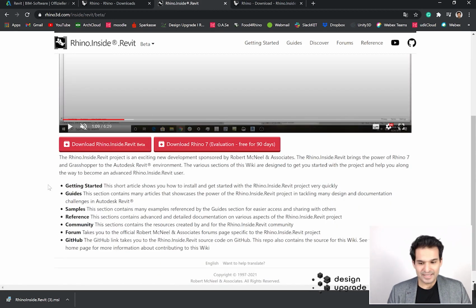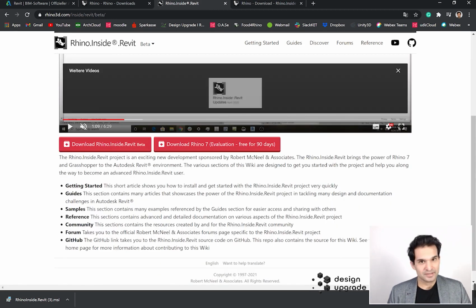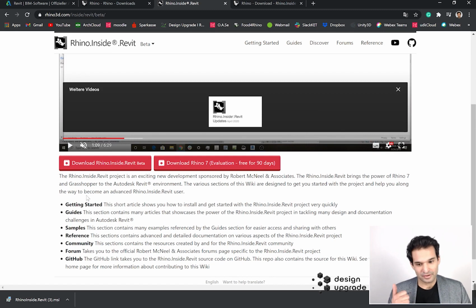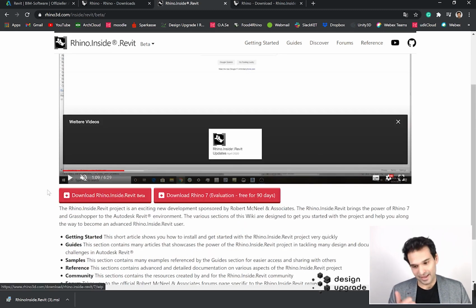The first site should be actually the one that we need from McNeil. Now they have a beautiful introduction video just explaining overall how to download it, just going through the processes, etc. It's more or less in a nutshell exactly what we just had. So we need to make sure that our operating system is up to date and we have the correct version. If that is in place, then all good. You can also download Rhino 7 here, if you need to, you can see 90 days. Otherwise, just download this Rhino.Inside Revit beta.